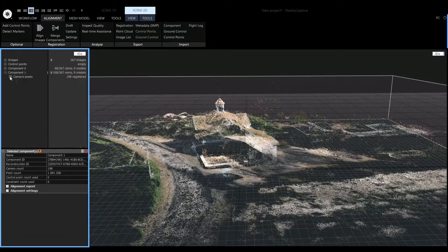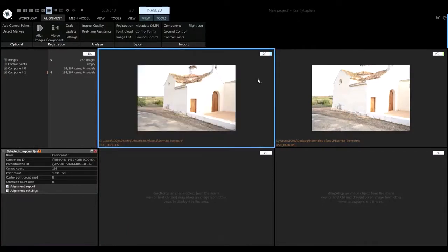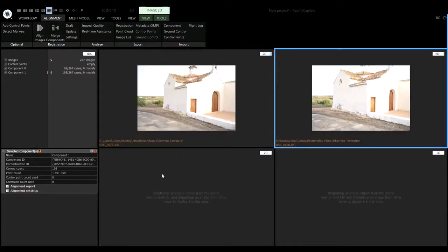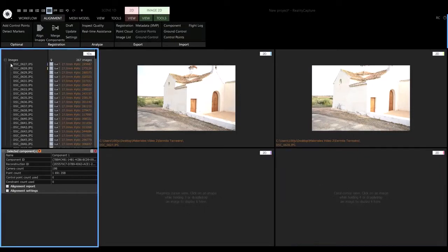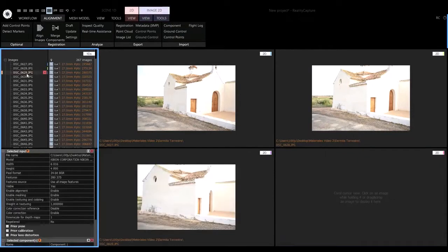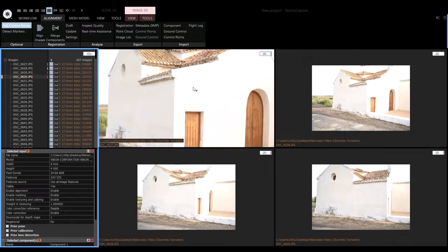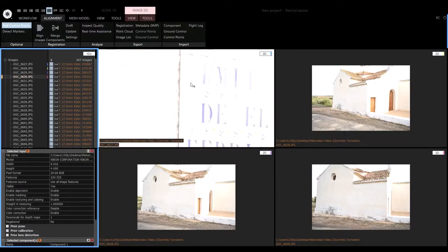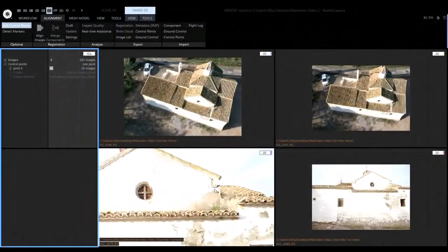To join both point clouds, it is necessary to manually set homologous points to indicate to the program that both components are the same element. We proceed to segment the layout in 4 windows. We mark as information to represent in each one 2D, and we give a color value to each one. Control 1 blue, Control 2 green, Control 3 lilac, and Control 4 magenta. Select the option Add Control Points and proceed to search the images for clearly recognizable points and mark them on the different images.